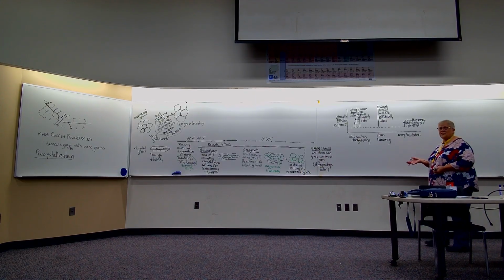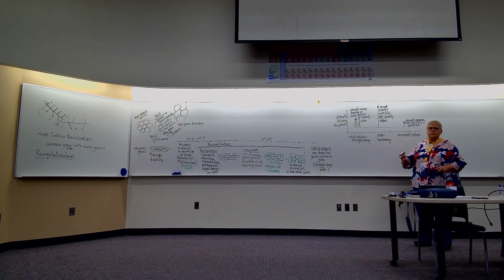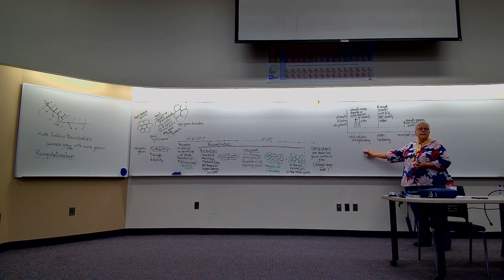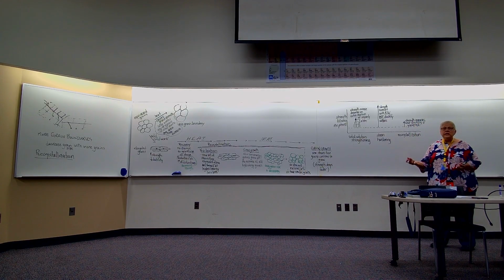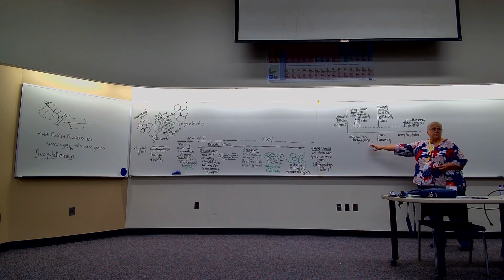Solid solution strengthening is probably the most expensive way to do this. Alloying requires a lot of heat, furnace energy. It requires another material. So it's probably the most expensive. But with solid solution strengthening, I could just make a stock of material from which I machine my parts. As far as hardening the surface, if I just need to harden this surface, well, this is the best way.